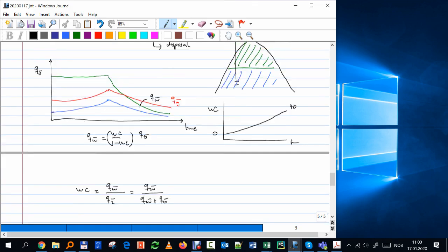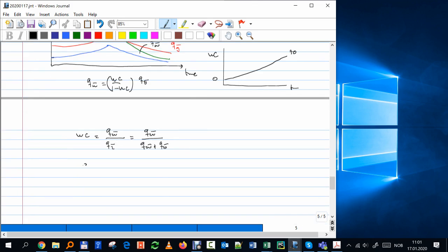So what I'm saying is that when Q oil is constant and the water cut is increasing, you should see an increase in the amount of water because of this equation. This one is increasing, so it's going up and up until the oil rate starts to drop, and no matter if this one is going up, this one is going to go down, because this part usually dominates. The same thing for gas, which is slightly simpler: Q gas is GOR times Q oil. For example, with solution gas drive, that's a GOR with time. This one might be increasing here, but this one is decreasing.